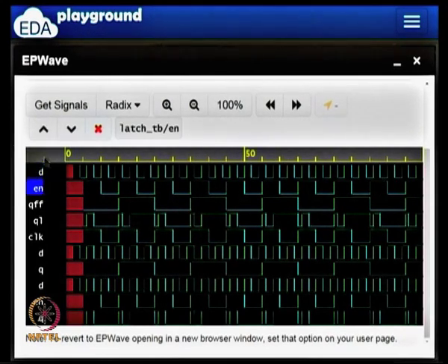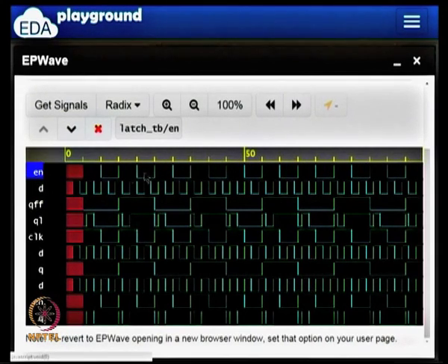So this is my clock signal, En is called my clock signal, D is my data input, QFF is my flip flop's output and QL is my latch's output. Forget all the lines below that, it is showing everything inside the design also. So if you have instantiated something, it is also showing all the signals as seen from inside the instance.